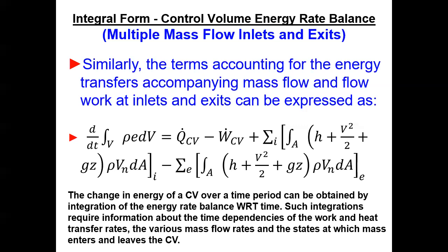So the change in the energy of a control volume over a time period can be obtained by integration of the energy rate balance with respect to time. Such integrations require information about the time dependencies of the work and heat transfer rates, the various mass flow rates, and the states at which mass enters and leaves the control volume.